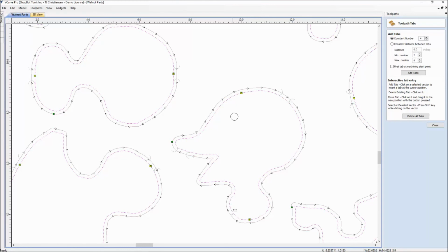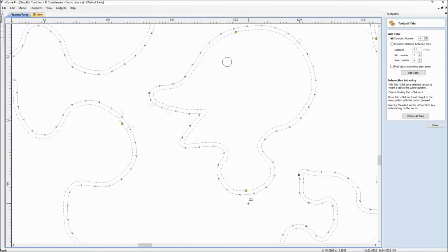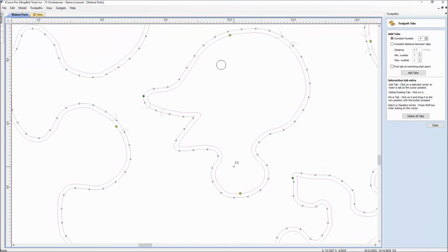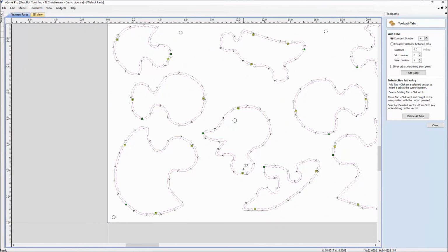Well, again, as far as cleanup purposes, I don't have to try to get a tab down in here. But how well is your cleanup? You've now placed a tab into an area in a jigsaw puzzle that is a pretty intricate spot. Are you able to clean that up precisely as the machine cut it? So again, think about your woodworking techniques, your shop, and your setup, and where you would put tabs.